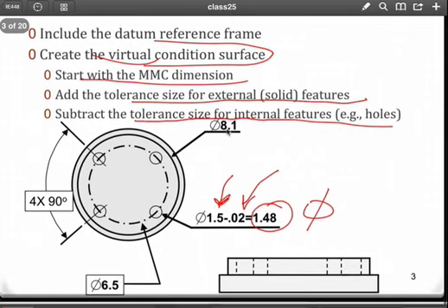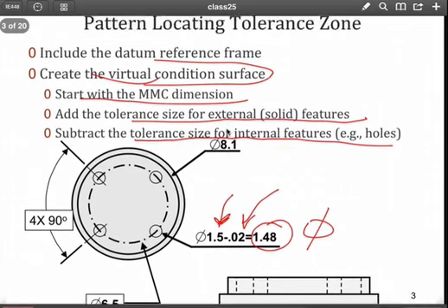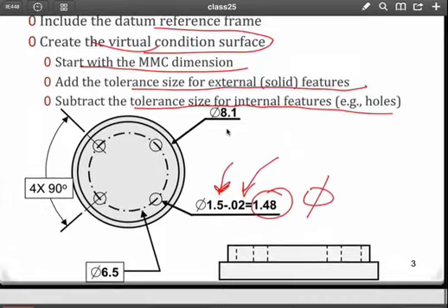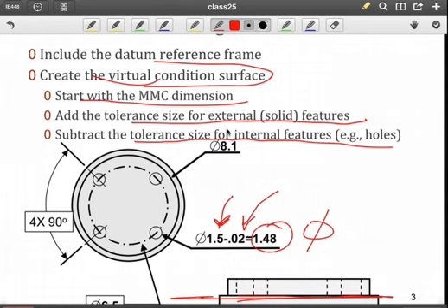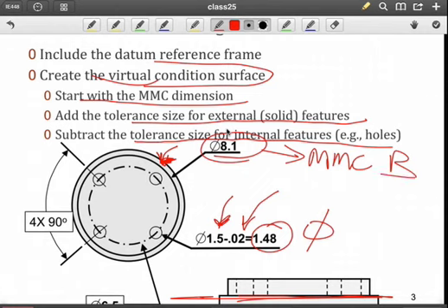So what we'll need is a locating plate, or three locators, as you can see here, to establish datum A. And then we're going to need something to constrain the location of the feature corresponding to datum B. And of course, that inside diameter should be 8.1, which corresponds to the MMC condition for B.